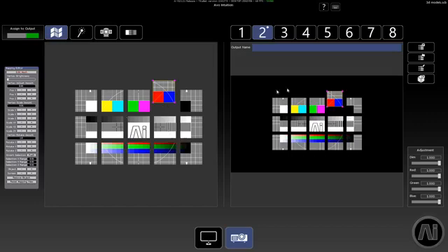But it does mean that you can use things like this remove object tool here in AI. Let's say that I was doing this as projection, from a couple of projectors, and I wanted this projector to only show those left 9. Because we've saved it as separate parts, we can use the remove object button, and then use the next object button to find the next one that we want to remove.